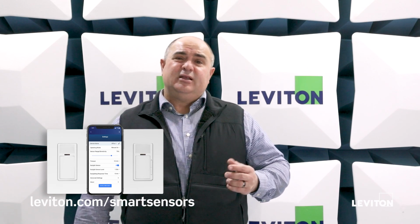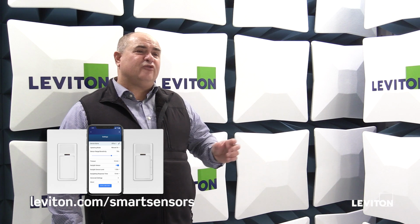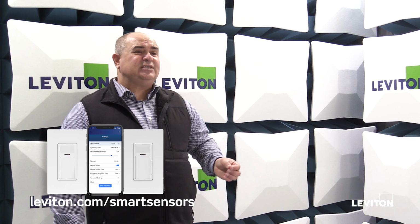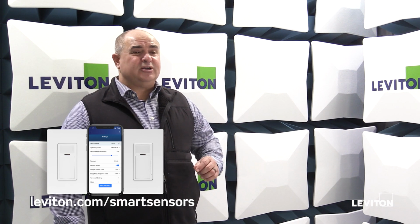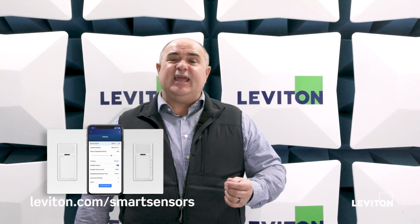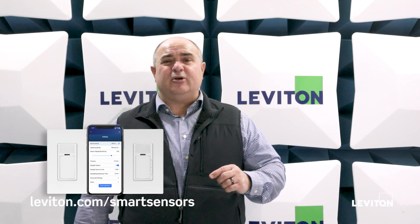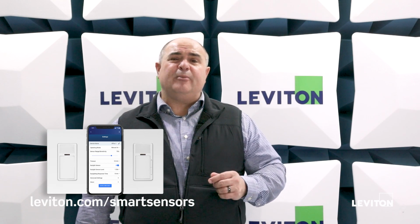And what am I saying? Well, Title 24, for example, now in the 2022 version has a requirement for a primary zone and a secondary zone. However, if there's less than 120 watts of light in the primary zone or less than 120 watts in the secondary zone, or if the total between the primary and secondary zone is less than 240 watts, it does not require daylight harvesting. The latest version of ASHRAE 90.1 actually has taken that down to 75 watts in the primary, 75 watts in the secondary, and then 150 watts in both primary and secondary.